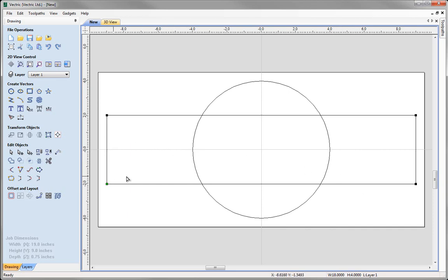Also, between each span we have a virtual midpoint, which is represented here, here and here on all the spans. And what we want to do is take advantage of those midpoints, and turn those into usable points. So to do this, we simply come over one of the virtual midpoints and right click on the mouse and click to insert a point. And again we can do that for the bottom one here and click to insert a point.